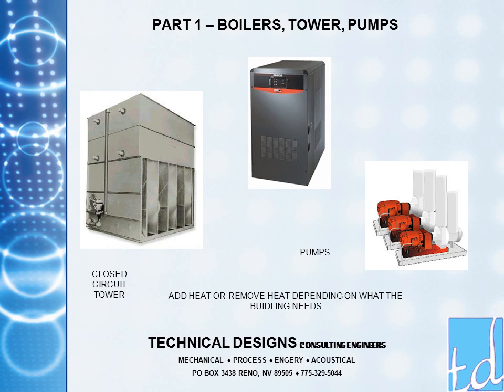We'll come back to the water source heat pump, but for now let's look at the other parts of the system. The mechanical room in the north part of Area 500 in the building houses the boilers, pumps, and cooling tower. The boilers are designed to heat both the condenser water loop and the hydronic heating loop. The hydronic heating loop goes out into the building and with heat exchangers in the bottom of each domestic water storage tank heats the domestic hot water.